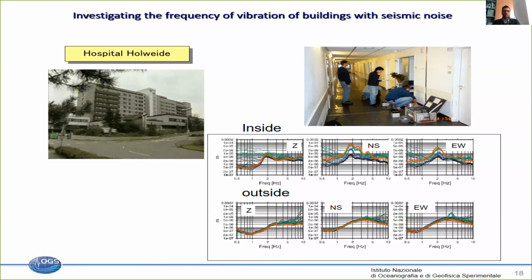Of course, the behavior of a building during strong shaking will be different from the behavior that we expect during the small shaking induced by ambient vibration and by this seismic noise. But at least they can be very useful in fixing some of these parameters for the starting behavior, let's say, of a building also during large shaking. Then we expect that the parameters will change, but at least using these methods, we are able to fix the starting parameters. So for example, these are measurements we have done many years ago here on a building that was